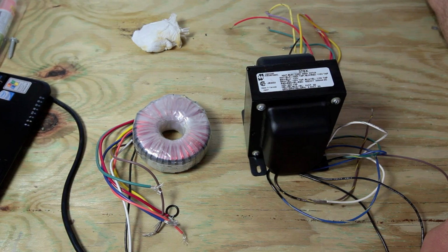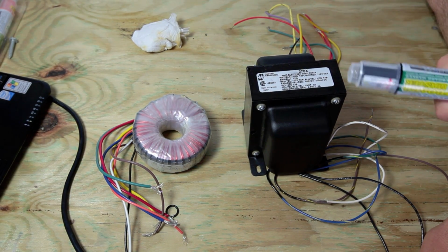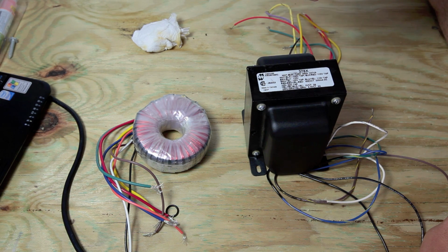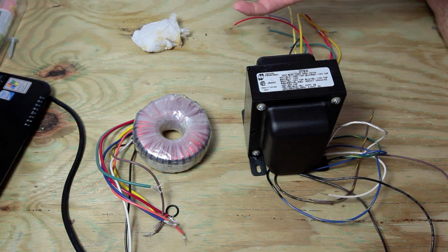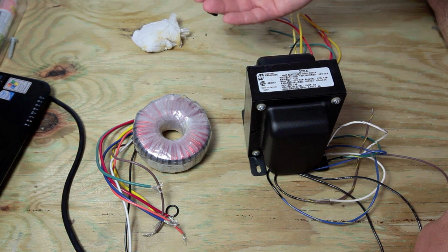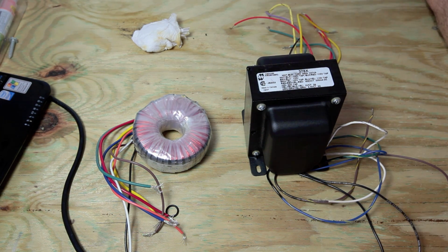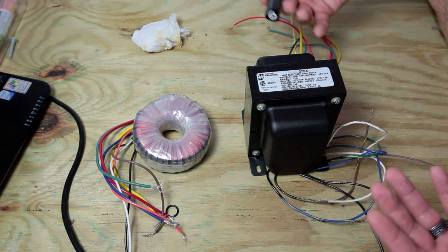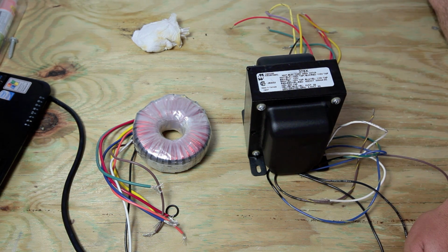Now, also worth a mention, I talked about losses and eddy currents in the core material, okay? Let me try to describe that. What happens, right? The core material is ferrous, okay? Ferrous material conducts electricity. And if you have a magnetic field that's cutting across that material, it will induce a current. That ends up being a loss, and that's why you never get the same power out that you get going in, okay?